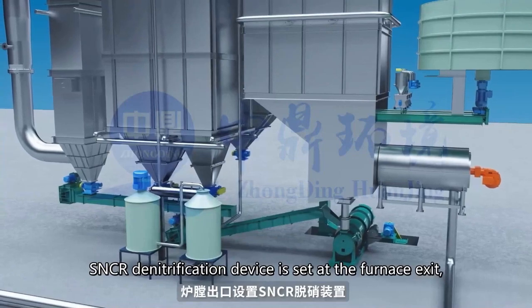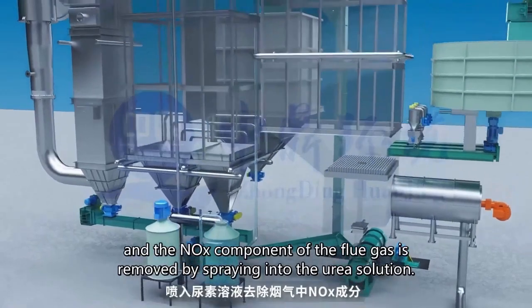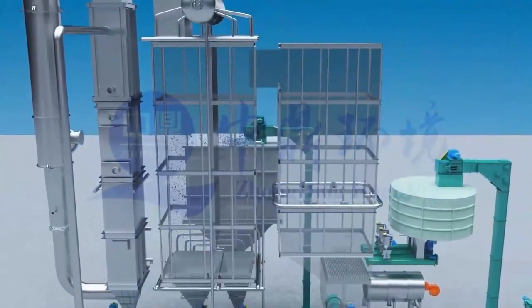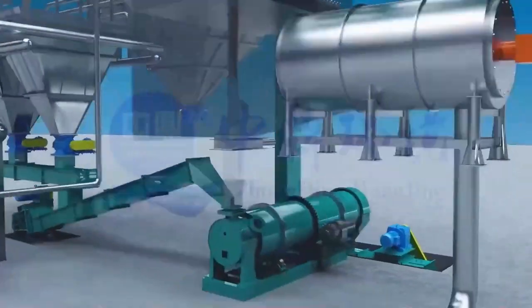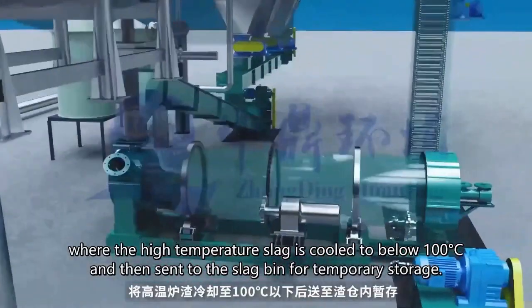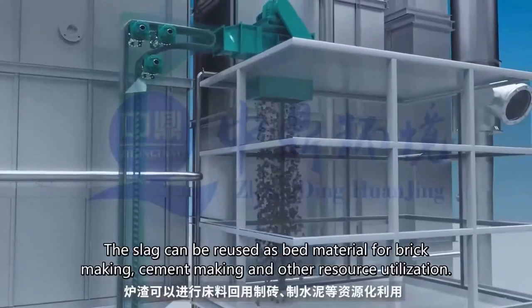An SNCR denitrification device is installed at the furnace outlet, using urea solution to eliminate nitrogen oxides from the flue gas. Slag is discharged into the drum slag cooler via the lower discharge pipe to cool it to below 100 degrees Celsius, then transferred to the storage bin for reuse in bed material, brick making, cement production, and other resource applications.